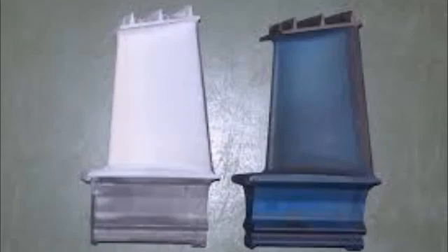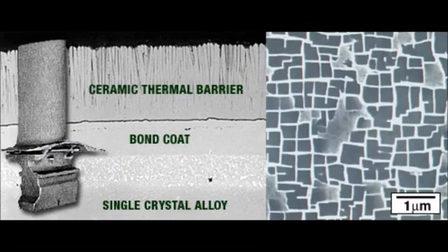The next step was to develop a coating to prevent oxidation and melting. In the 1970s, as the superalloy development proceeded, aluminide coatings were being added to the blades. This thermal barrier coating increased the blade's capability to resist the constant heat. Even greater than the aluminide coating, ceramic thermal barrier coatings were being applied to the blade, starting in the early 1980s.